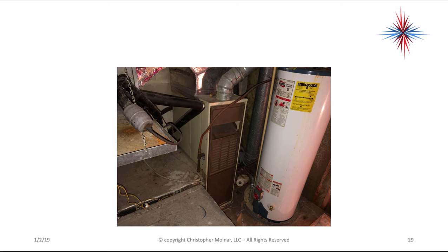So they were doing their temperature readings, they were taking their required readings, but they were actually adjusting down the refrigeration effect in the unit rather than fixing the airflow. Airflow is important.